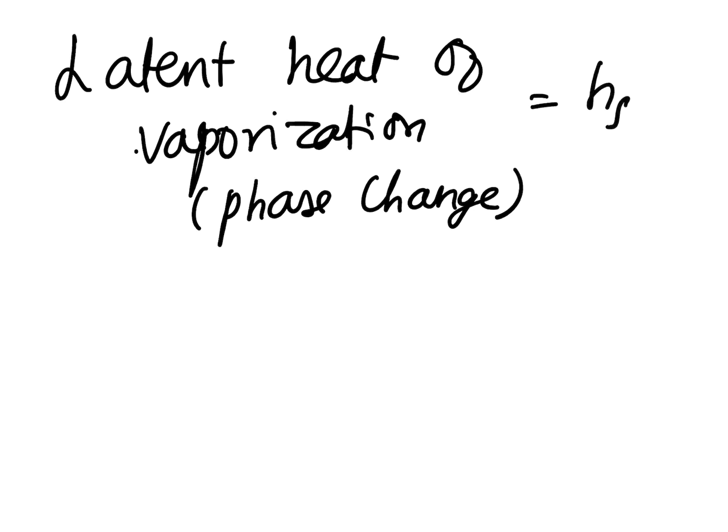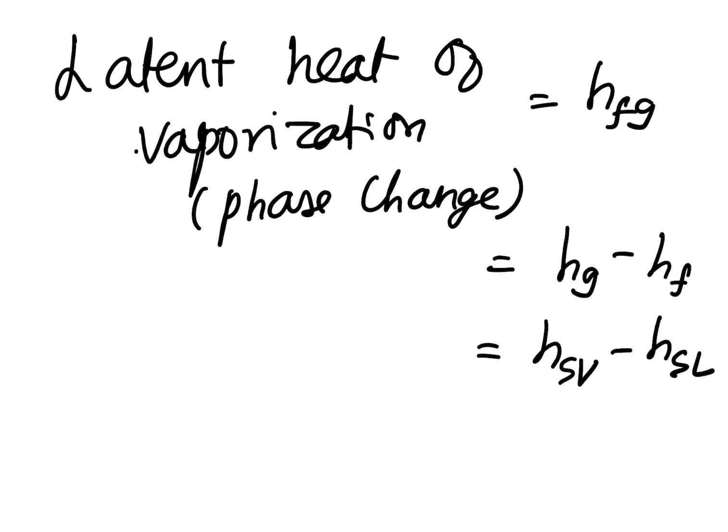This would be exactly equal to hfg, which is hg minus hf, or the enthalpy of the saturated vapor minus the enthalpy of the saturated liquid, both of which can be looked up from the tables.